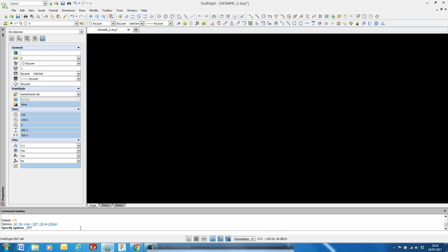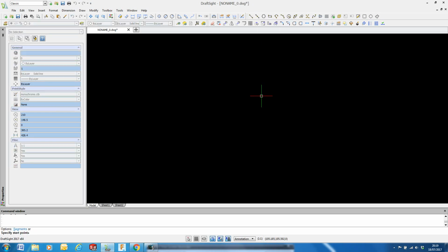This is what we call model space, and when we produce a drawing, we'll produce a drawing on one of the sheets, so it doesn't really matter where you're drawing in model space, but for simple stuff we might draw from the origin, from 0, 0. We're going to draw some lines from anywhere, but we're going to draw them at a known length. So starting anywhere, left click.